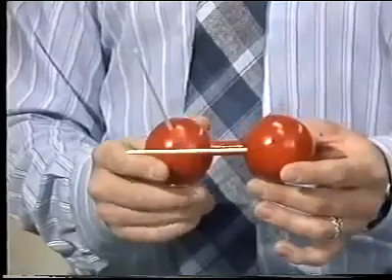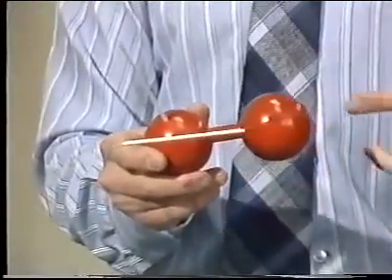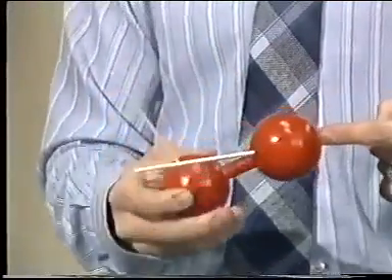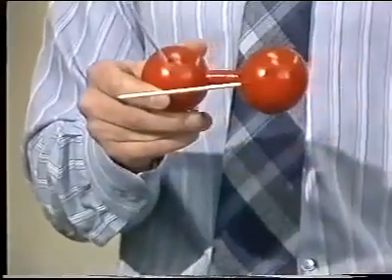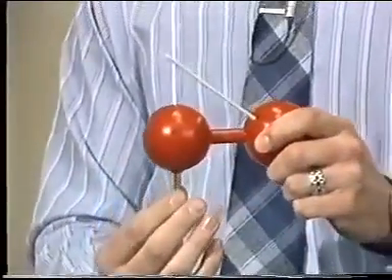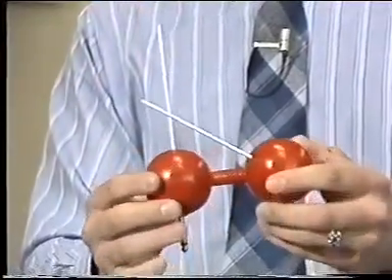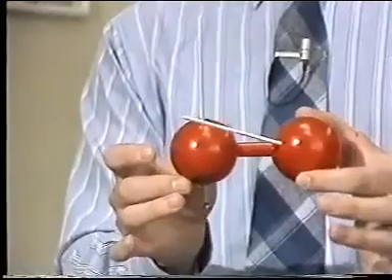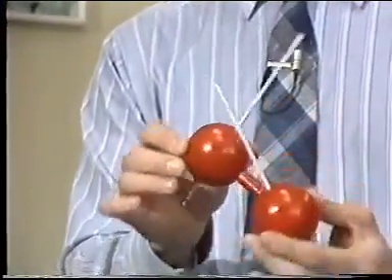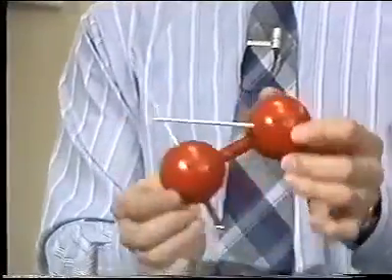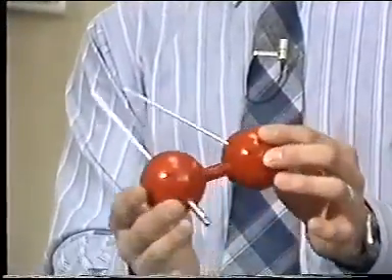Okay, so we've now looked at the kinematic structure. What about the geometry? Here we have a link from this system. It is a binary link because there are 2 revolute pairs on it. Here's one, and its axis is marked with this white rod. Here's the second one, and its axis is marked with this white rod. Now, in this configuration, those 2 axes are skew lines in space. They do not intersect and do not have any special geometrical relationships.